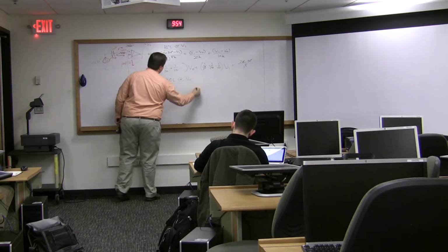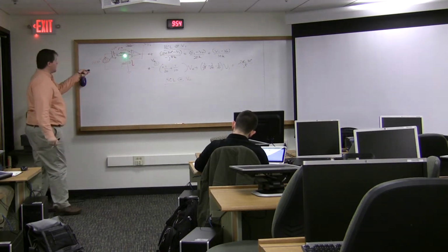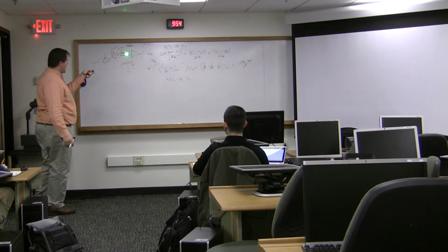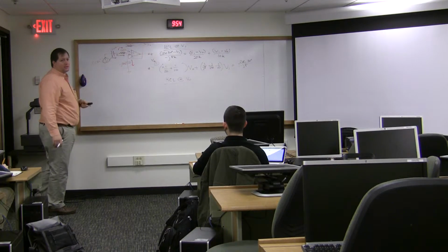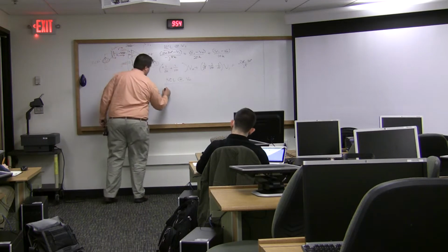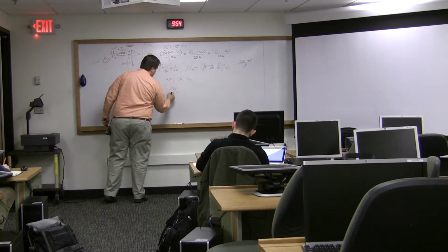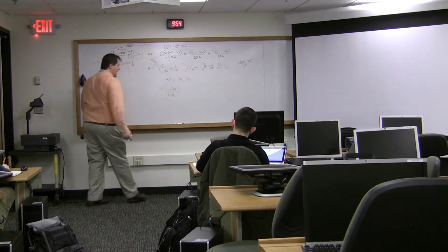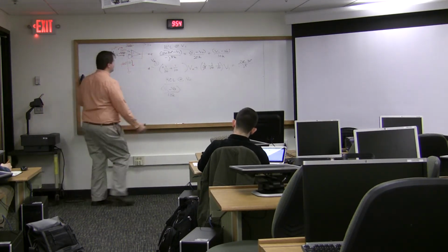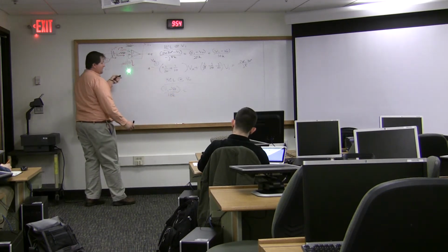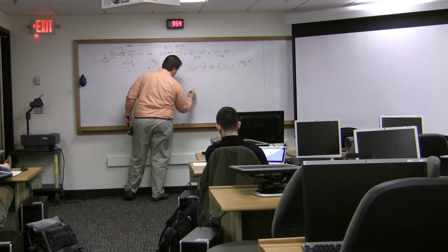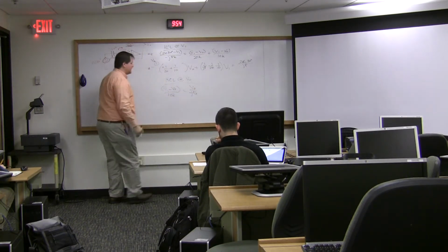All right, so let's do KCL at V0. So now I'm looking at this point, and I say, well, currents in, that's this one, equal currents out, that's this one, because no current flows into the input, right? So I just have 2, V1 minus V0 over 10K equals V0 minus 0 over negative J4K. Again, the Ks cancel out.